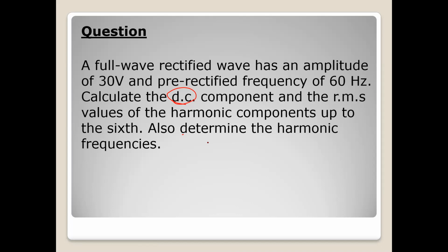First of all, what do I mean by even harmonics? Even meaning that they're multiples of 2 of the fundamental frequency. So what's the fundamental frequency? The same frequency as the rectified wave, which would be 60.